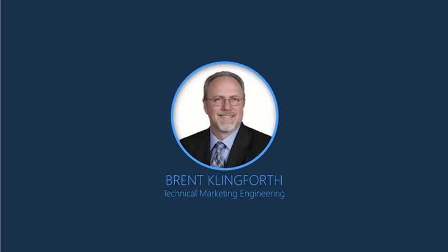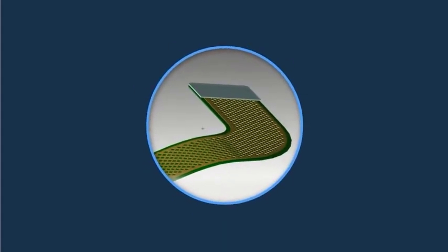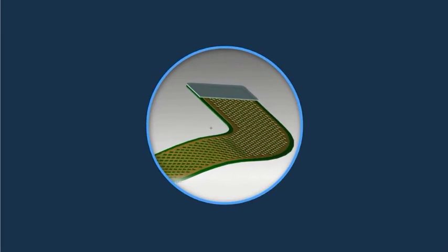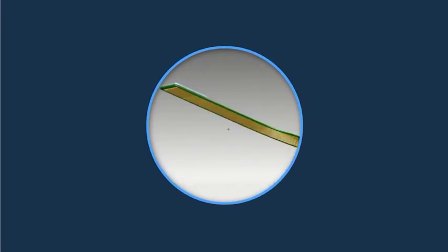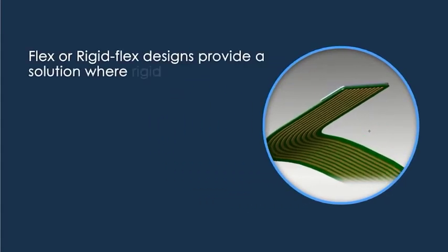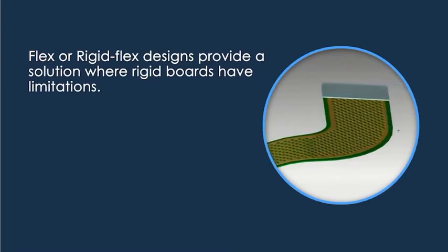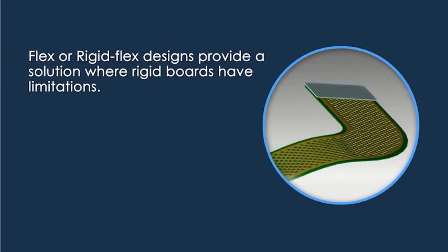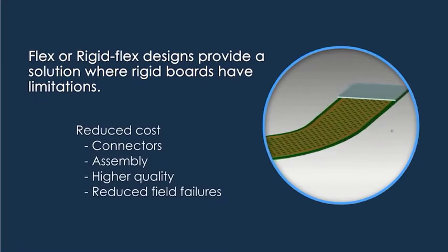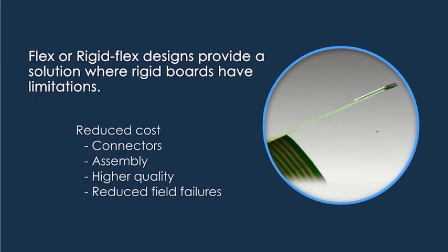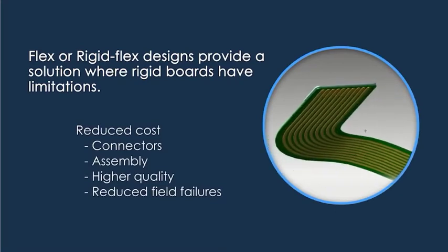I have a feeling many others listening today do as well, that more and more products are being introduced, or existing designs, depending on the industry, are being pushed to reduce form factors. Flex and rigid flex, in most cases, is the answer. Sectional boards interconnected with flex can be used to wrap electronics around an arced or circular object. Cost can be reduced by eliminating connectors, cables, and assembly steps, or boards can be folded on top of each other when surface area is limited.